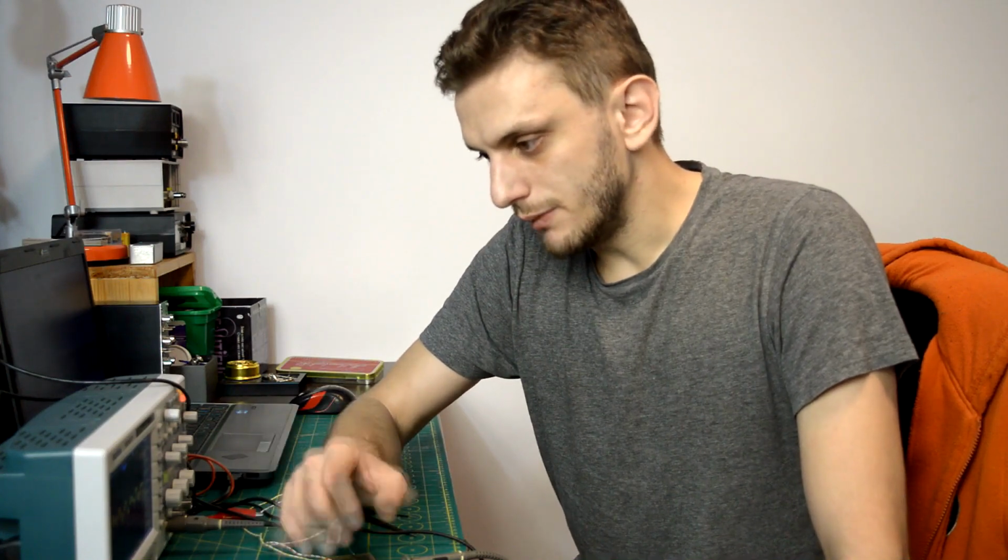Now a better way of seeing this would be using a spectrum analyzer, or if the FFT function on your oscilloscope works very well, then you can see this change also with that. But just by looking at the waveform, it's pretty obvious that changing the bandwidth has completely changed how the noise the circuit is generating looks like.